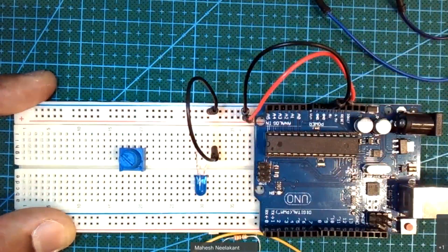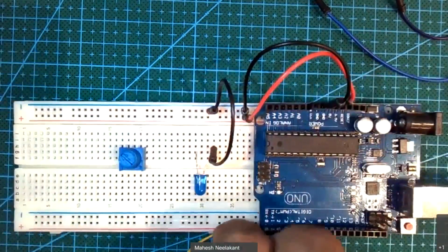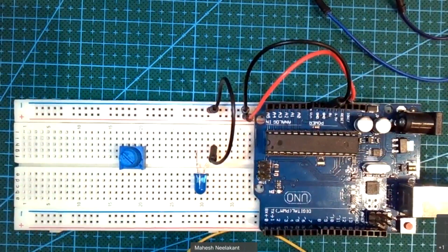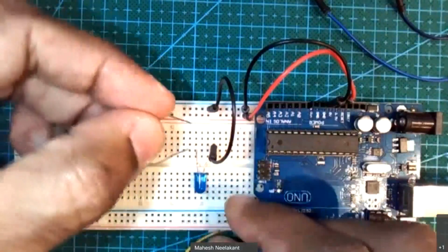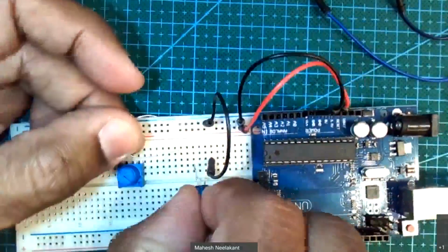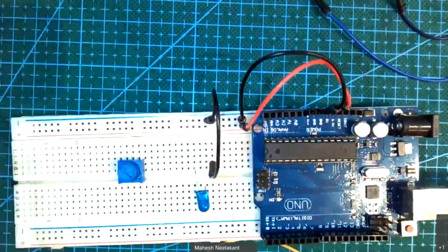And before I can connect up the data, or the thing to turn that on, I need to protect this LED. And to protect the LED, it says use a 330 ohm resistor. So I'm actually going to move this up a little bit so I get a few more pin spaces right here.